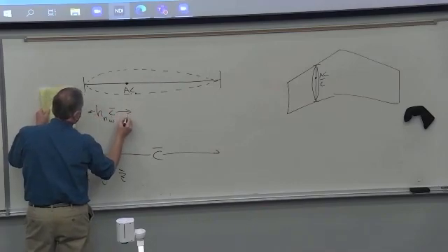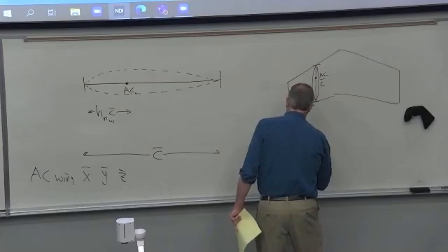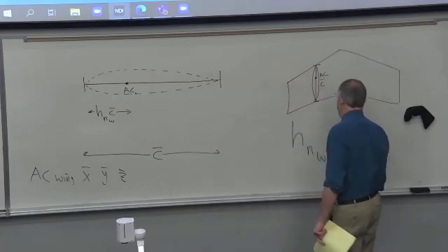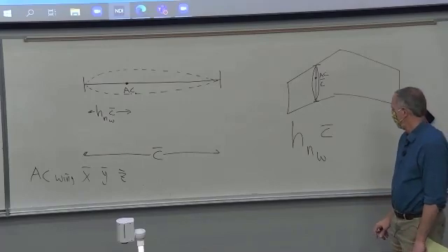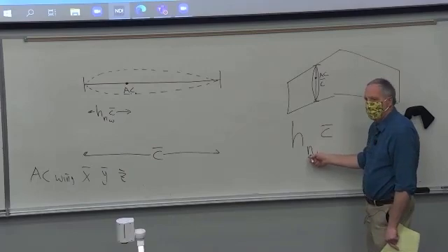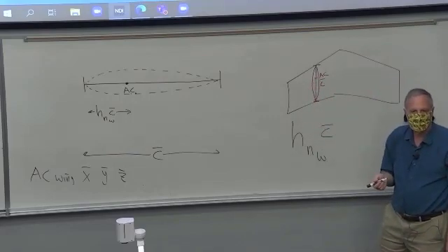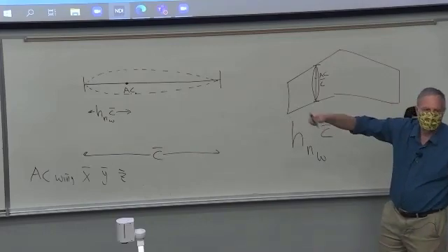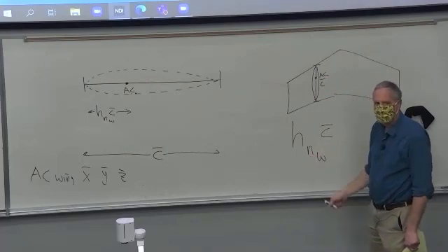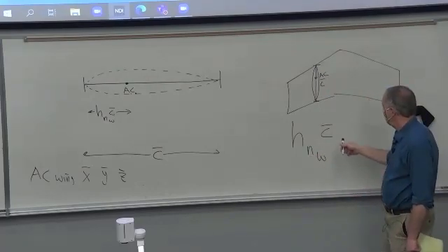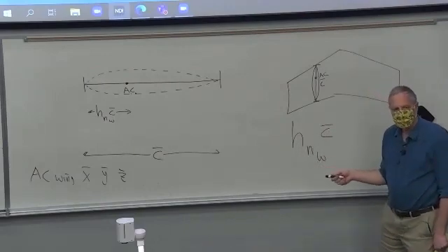Here's our first term that we're going to define. It's called H subscript N subscript W. I'm going to write that over here. H subscript N subscript W. And then it's multiplied by C bar, and that's that distance. So N stands for the neutral point of the wing, which is where it's the aerodynamic center or the neutral point of the wing. It's where the lift, the net resultant lift acts. And that's what we were talking about in the configurations. The neutral point is the net resultant force location. So for the wing, this is the net resultant force location. For the wing, that's why we put the W. And notice that it's non-dimensionalized with respect to C bar. In other words, this doesn't have dimensions, and we multiply by C bar. And I'll show you why we do that.